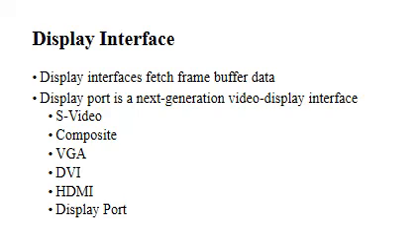Now, VGA. VGA is still popular even though it has been around since 1987. It uses analog signals. The plugs and sockets are blue and have 15 pins. Cables can be up to 15 meters in length, although 50-meter high quality cables also exist. Then DVI. DVI became popular in about 2005 as a digital interface.